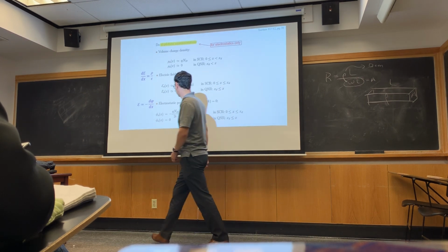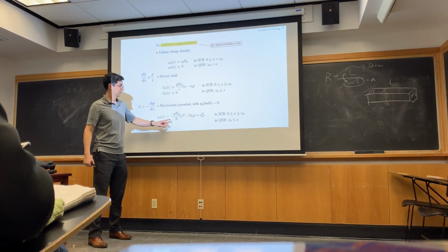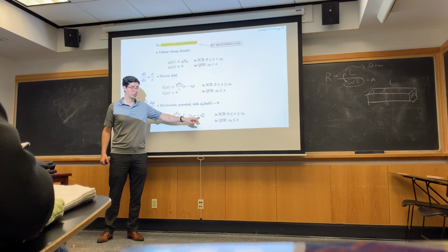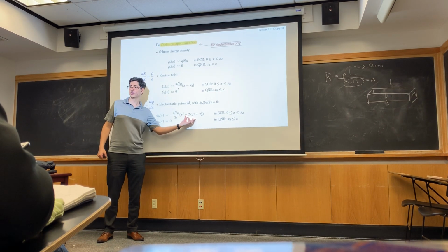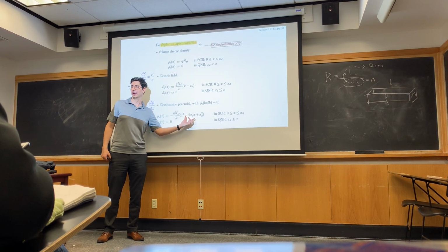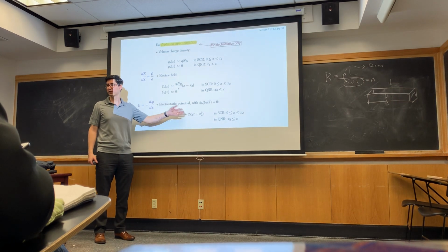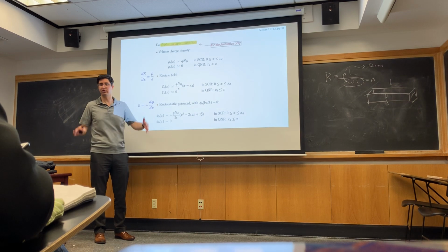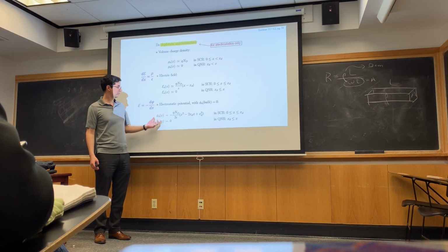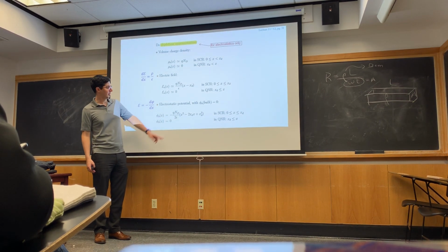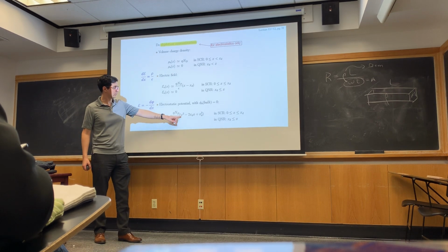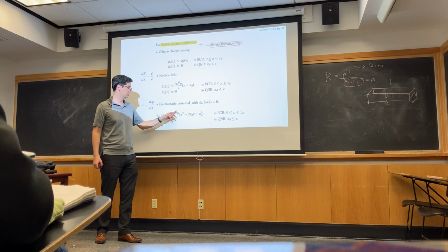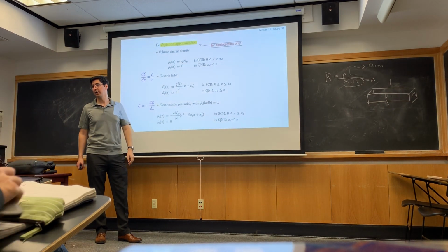So this potential at xd is xd squared minus 2xd squared plus xd squared. What is that equal to? 0. I also forced my potential to be 0 there. This could have been something else, but that's what I chose as my reference. Well, what is my potential at 0? The potential at 0 is 0 minus 0 plus xd squared times qND over 2 epsilon.